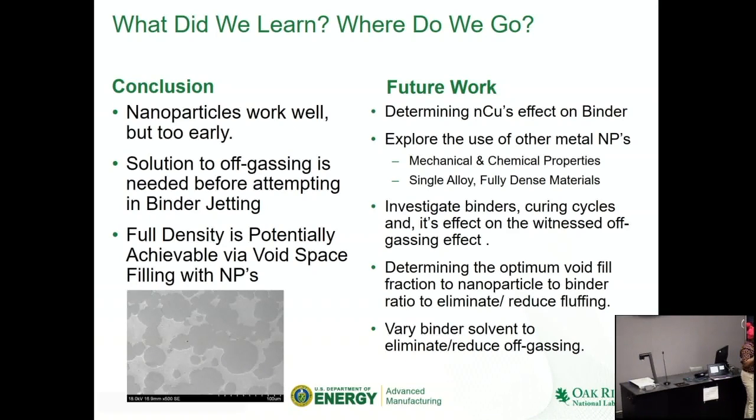The conclusion is that nanoparticles do work very well in terms of their packing, because it did increase the packing factor. But we need a solution to the off-gassing before we try to actually put nanoparticles into the binder, which is selectively deposited into the particles. And full density is potentially achievable by filling that void space.